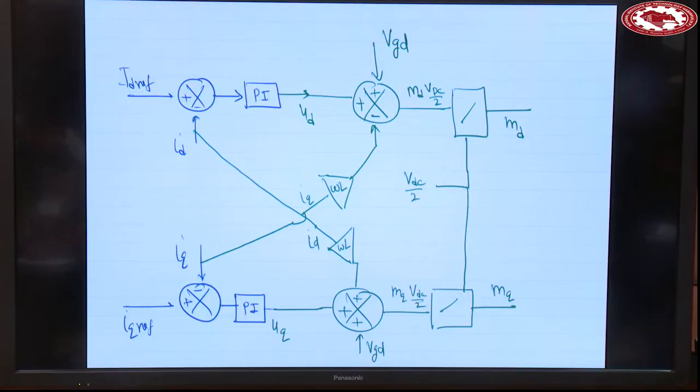Today my tutorial and the professor's lecture are going in a very synchronized way. Today he discussed PQ control, power control through current. So this is actually the current controller, using a PI controller, it's not LQR, so it's partially feedback.